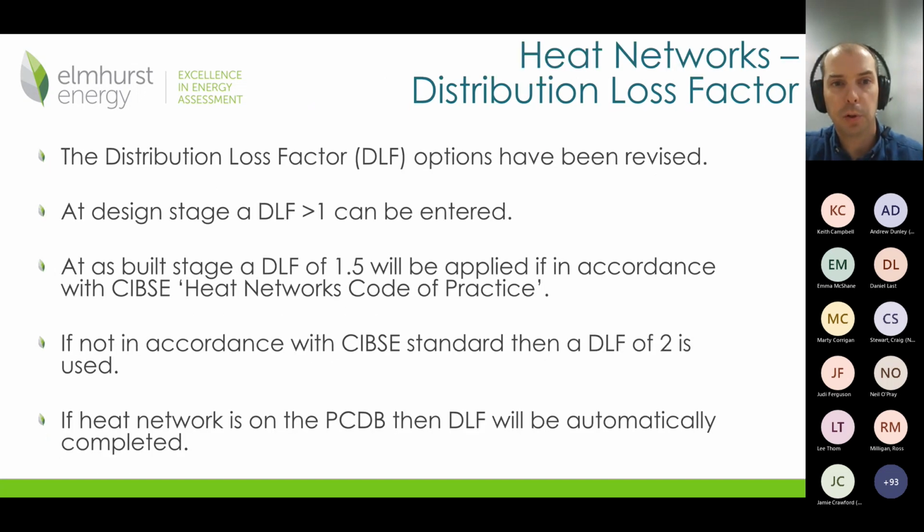There's some changes to distribution loss factors. How SAP assessors reflect the loss factors from heat network pipework has changed. You now have to say whether it matches a CIBSE code of practice or not. If it does, you get a DLF of 1.5. If it doesn't, you get a DLF of 2, which is quite penalising for the calculation.